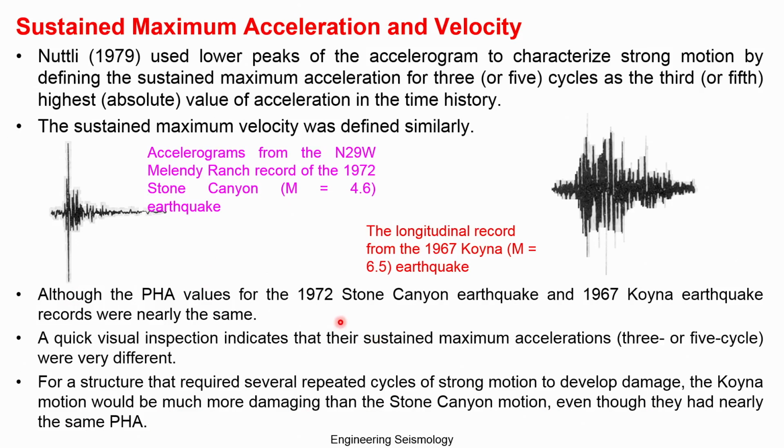So when you have a higher sustained acceleration, you can expect a higher damage level than the PHA alone suggests for the same earthquake.